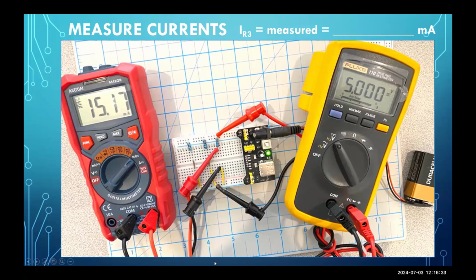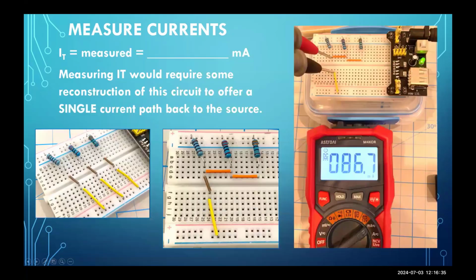How do I measure total current? Well, I'm going to have to physically change this circuit, because if you look at the original circuit that I have on the left, there is no single point that I can break open singularly in order to stick my ammeter in. I've got three separate branches hooked up to the blue rail separately. So I'm going to need to rebuild this slightly.